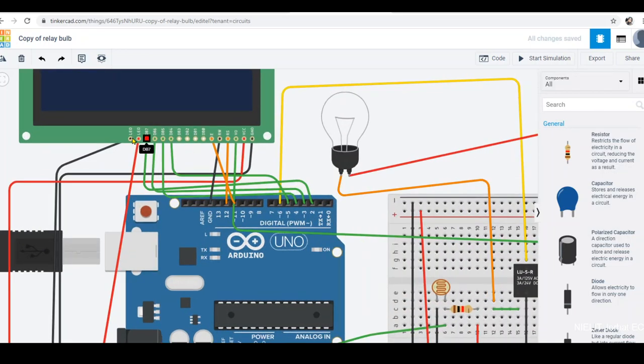You see, if I zoom it, you will see there are total 16 pins. Okay, 16 pins. Out of this, DB0 to DB7, these are the data pins. That means if you are going to write something into the LCD or read something from the LCD, these data lines will be used. And above that, some other pins such as ground, VCC, V0, reset, read write, enable pin, okay, LED high, these are for backlight, means to light up the LCD we use these two terminals.